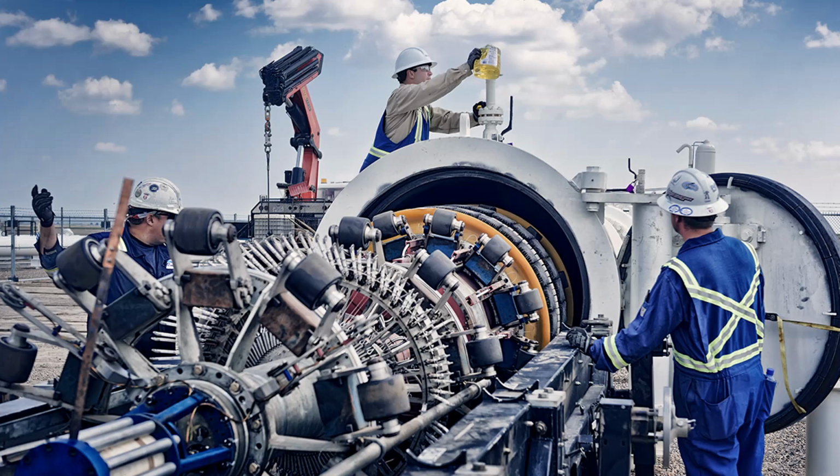You give these vendors a set of rules. There's a corrosion clustering rule that tells you if different anomalies are interacting with each other. And then there's a corrosion burst model that tells you the pressure at which that anomaly would burst the pipe. So you give them these two inputs, they run their tool, and they essentially tell you what to repair.